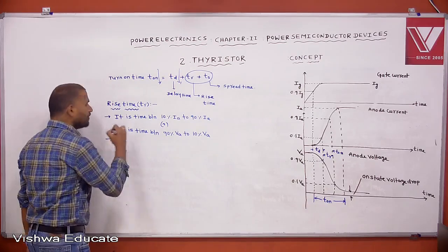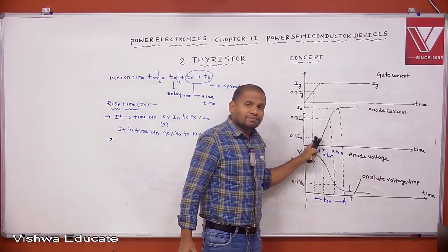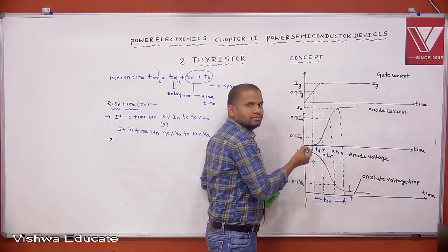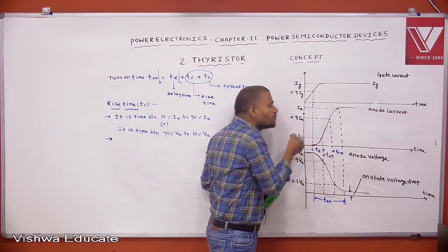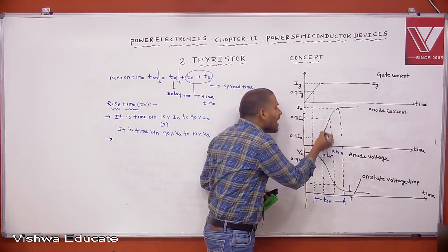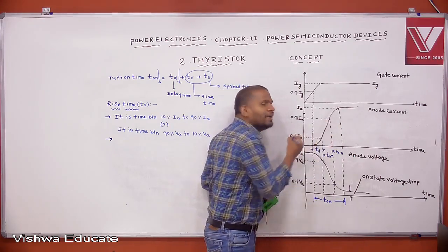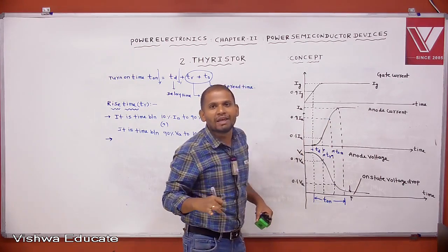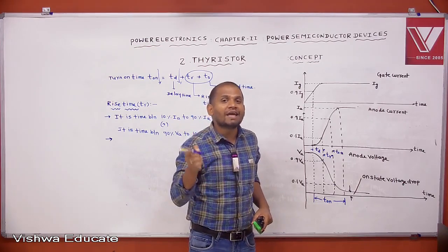Very important observation. Concentrate. During rise time, there exists a sudden change of current. During delay time, current is very small, associated with a small area. But whenever time enters the rise time, there is a large di by dt. Because of large di by dt, high current is associated with a small area, so there is high current density.